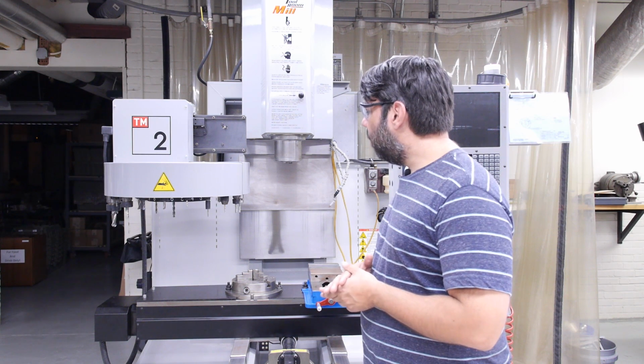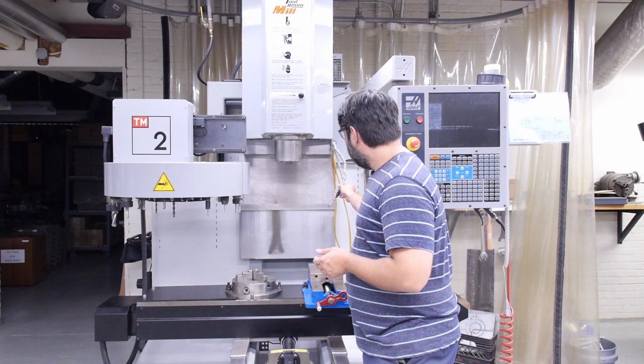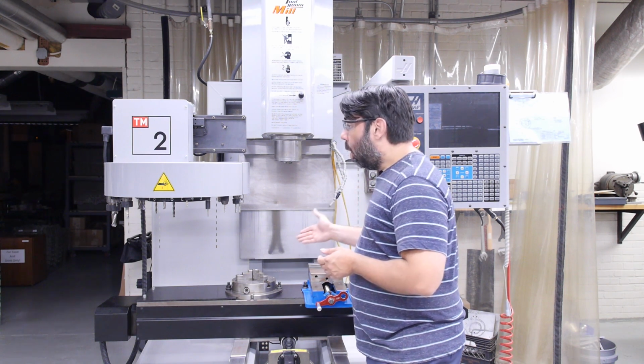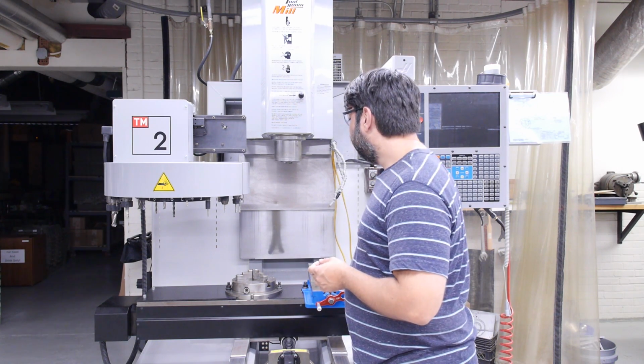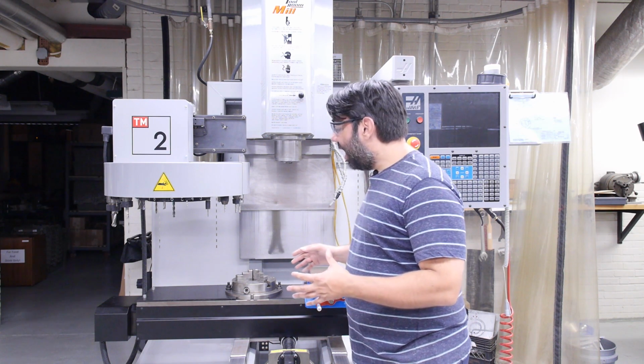The fourth and final advantage that we're going to talk about with the students is the ability that most CNC machines have to use either high pressure air and oil mist, as we have on this machine, or high pressure liquid coolant, like we have on the VF2 CNC milling machine, to flush chips out of the cutting zone, ensuring that they don't get recut, improving part accuracy, improving part surface finish, and keeping the tools and the workpieces much cooler. Those are the 4 advantages we want to highlight, and then there are 4 disadvantages that we wish to discuss with the students as well.